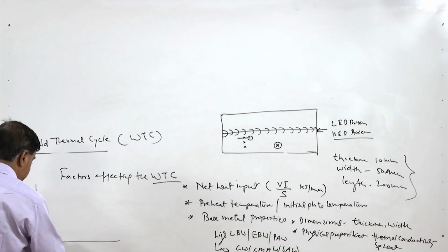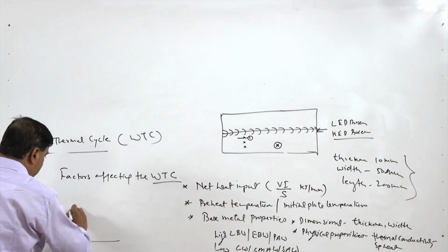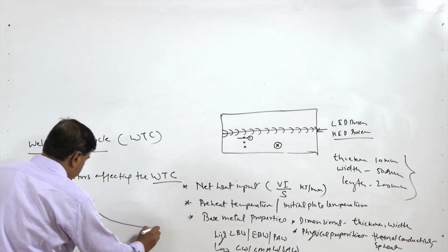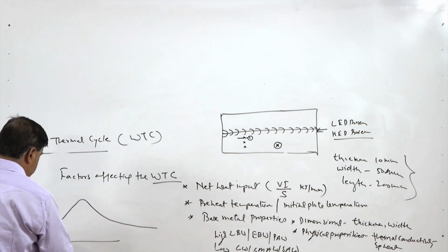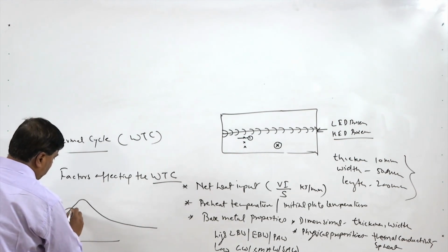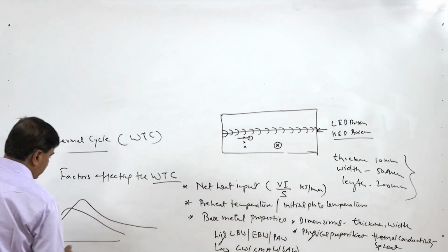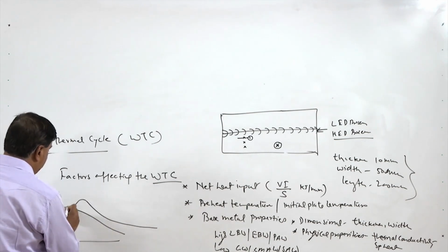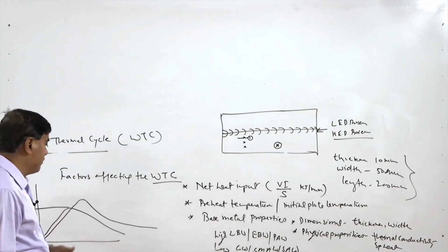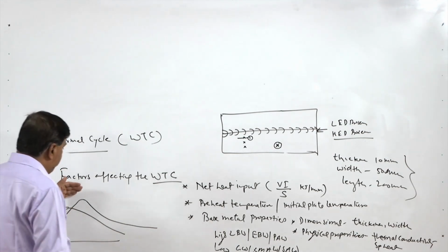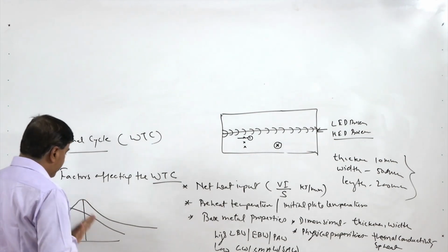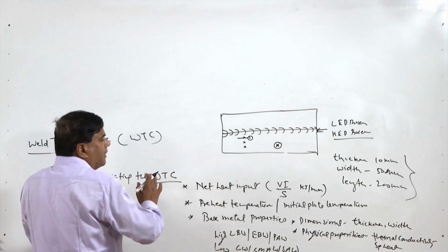In case of low energy density process, we will be getting higher peak temperature and then lower cooling rates. It is possible that we may not reach too high a peak temperature and then cooling will start like this. So, the peak temperature is actually reduced because we are not delivering much of the heat if the point is located away from the fusion boundary, and it will take, in case of low energy density process, of course, longer time, but it will take a lot of heat also.